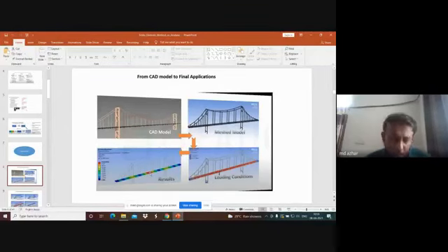It will give an indication to the engineer that this particular region is a critical region, and we are going to monitor it for failure. Maybe you can plan the maintenance, maybe you can strengthen that region more, maybe you can have a composite based structure where the material can be of higher strength.